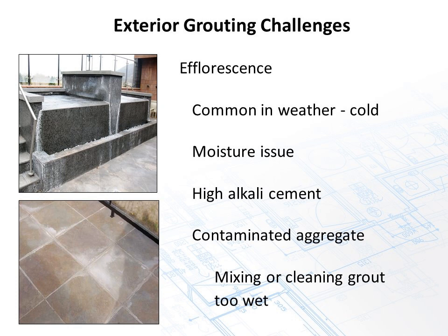Efflorescence is pretty common in cementitious grouts, especially used exterior. You commonly see it in colder weather, where the moisture doesn't migrate out of the cementitious grout at a normal rate because the temperatures drop. The water seeks salts out of other materials. Again, could be the substrate, could be the setting material. When it warms up, the water evaporates and leaves this mineral behind, or white water-soluble alkali material.